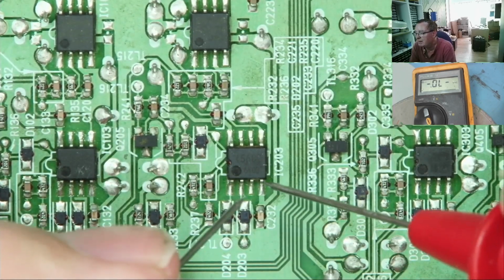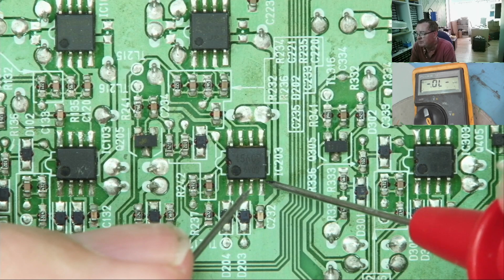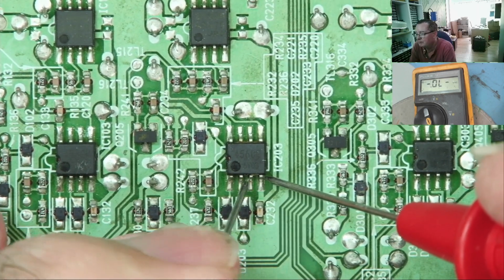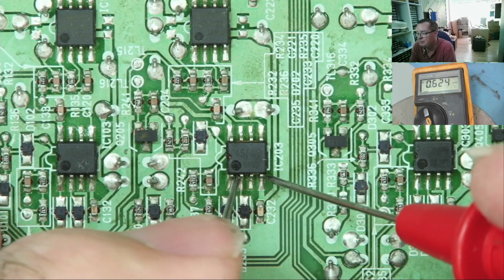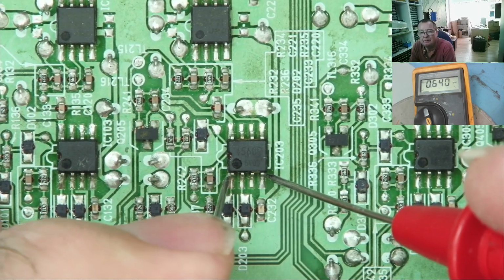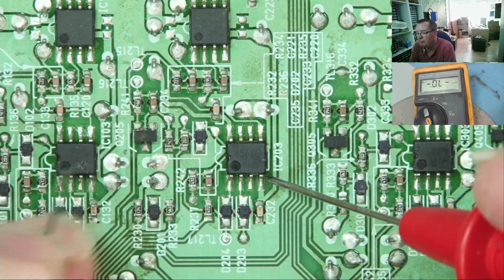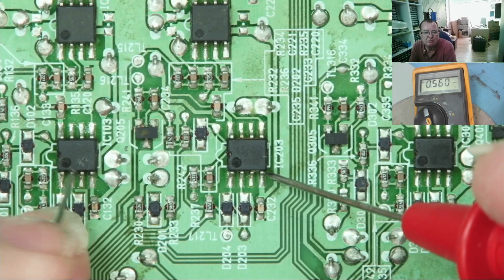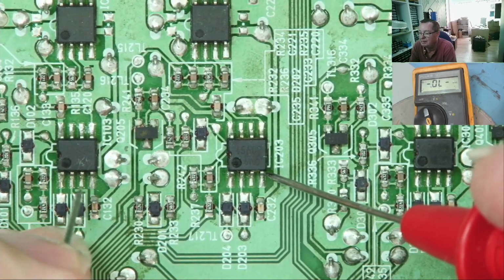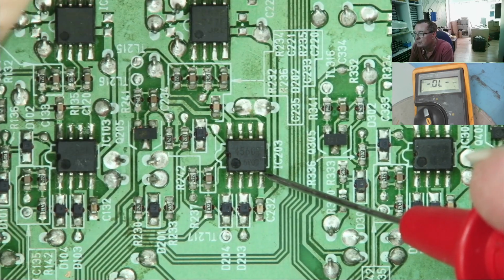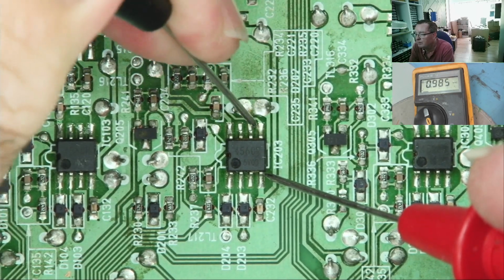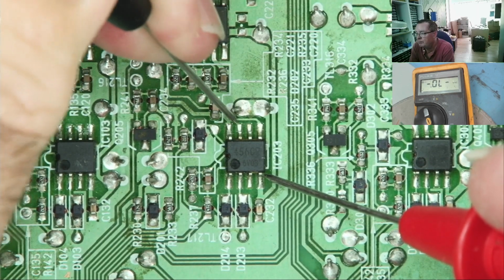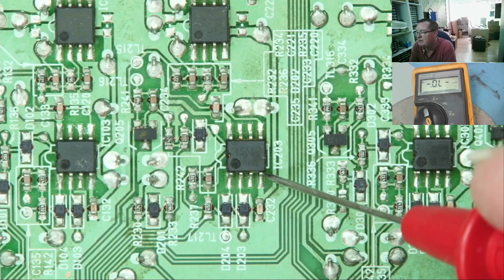Here's another chip of the same sort. Let's go again and see if it reads basically the same. So 559, 624, slightly higher. 640. So again, this one reads a bit lower like it did on that one. We should be able to read from here because this ground supply will be the same as that one. On the other side, 608, 624 output. And they read about the same as each other.